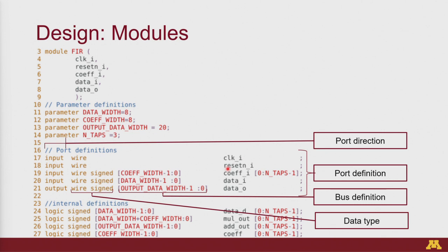An unpacked dimension is saying that each one is an individual element and you cannot work on it as a whole. For example, in the packed dimension, if I want, I can assign all 8 bits at one time. But in the unpacked dimension, I can't assign all 8 at once. I need to assign it one at a time because there's nothing which says the whole set together represents anything. Does that clarify your question?